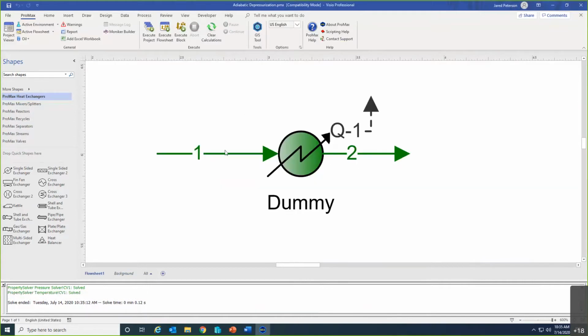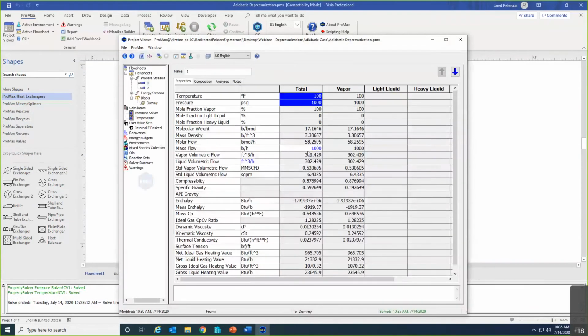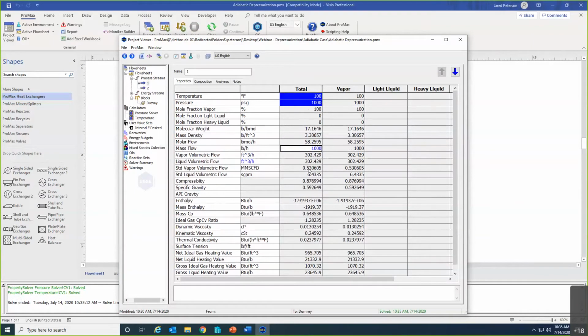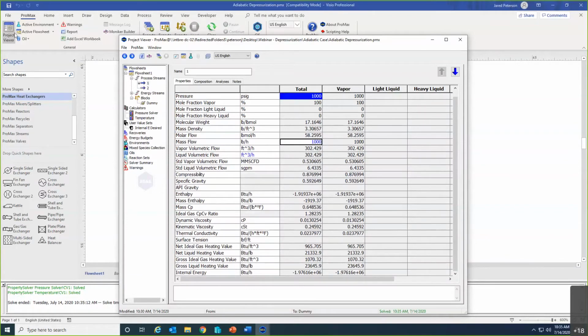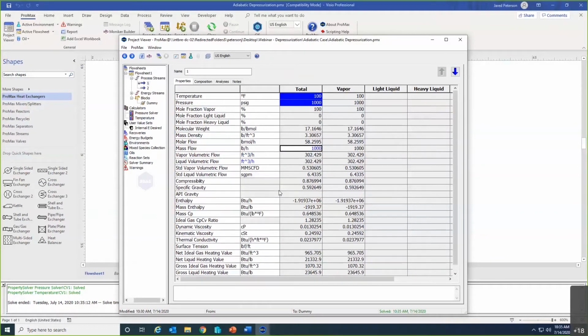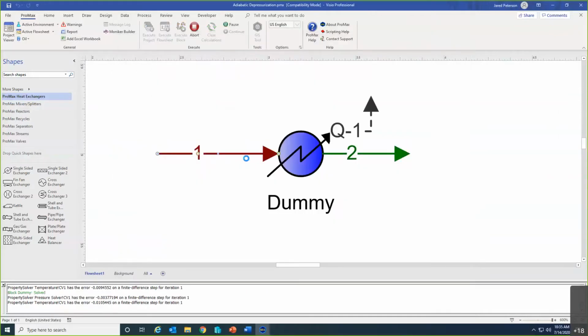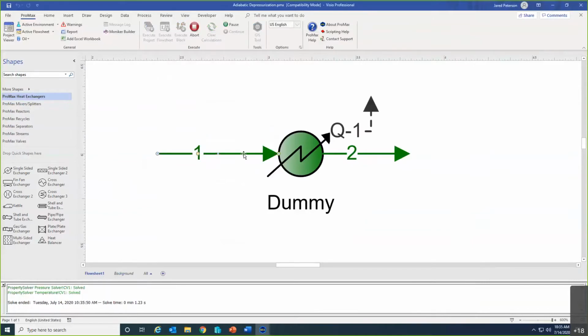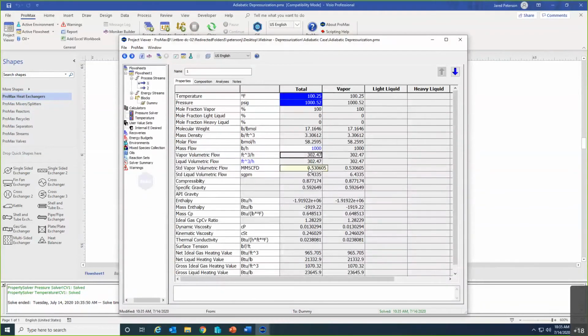So now we've got a system. So if I change the mass, let me just show you here. What it will automatically do is calculate the new temperature and the new pressure to achieve whatever internal energy I set there. So if something happens and I go down to 990 mass, I solve this, you'll notice it runs around a bit, and it solves for a new pressure and a new temperature at those conditions. That's what we want it to do. Now, of course, we are going to want to adjust our U value. You'll notice these don't solve to exact numbers.